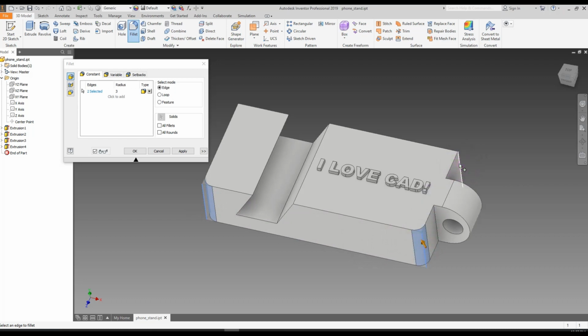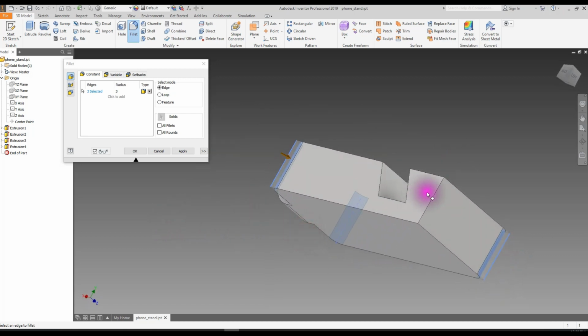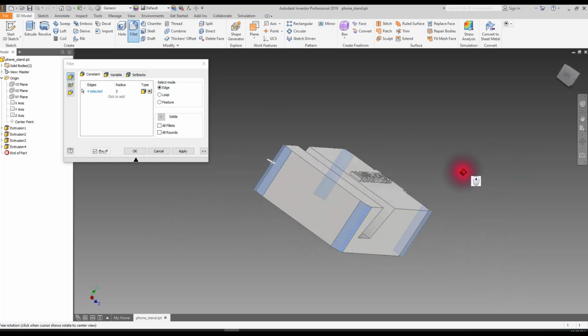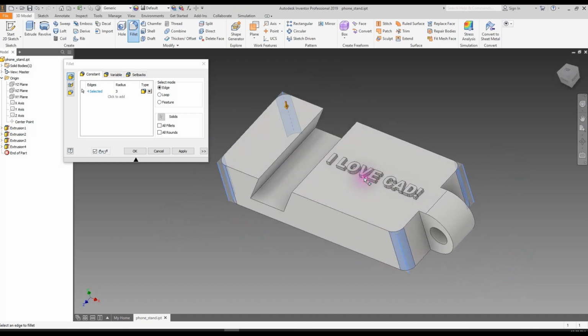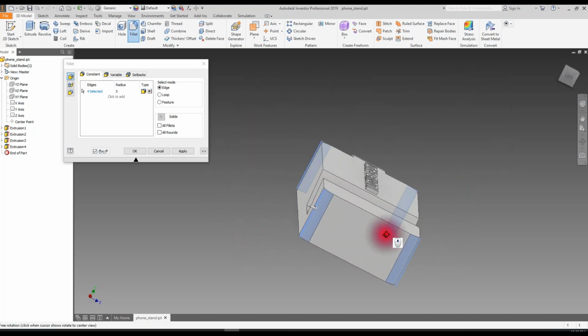People may also call this filleted. Maybe not technically correct, but that's all right. It's the fillet tool. So let's round these edges. And there we go. If you accidentally click an edge, just, oh, I didn't mean to round that edge. What you do is you hold down the Shift key on your keyboard, and you click on that line again, and you will unselect it. So we have selected the 4 corners we want to have rounded.